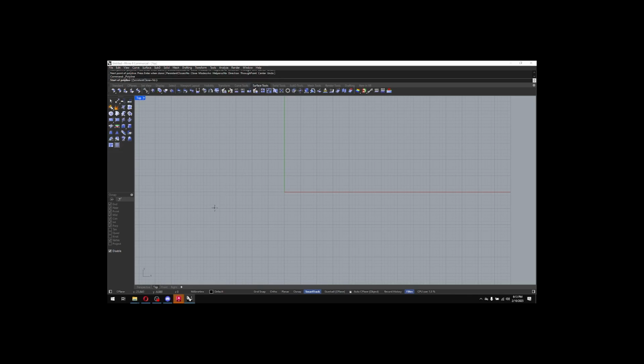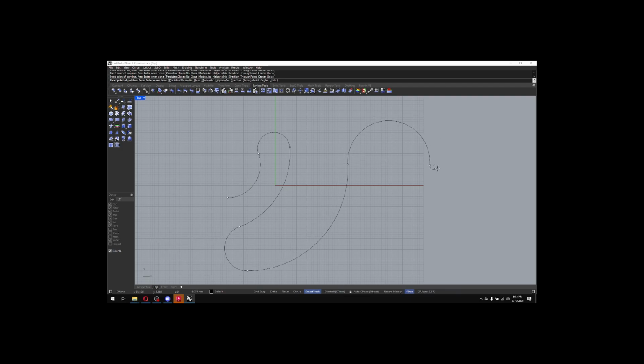Polyline's pretty basic though, so we'll just stick with a typical sort of shape. That's a good example, it'll also stay in whatever mode it was when I stopped the last command. So this one was already in a curve shape, so it stayed curve shape. I can type L, enter for line, back in line. Then I hit enter, it's in. If I do the command again, I'm starting in straight segments. Last thing to really cover on Polyline, even though there's tons of options in there, worth exploring. We'll touch on that in later sessions as well.